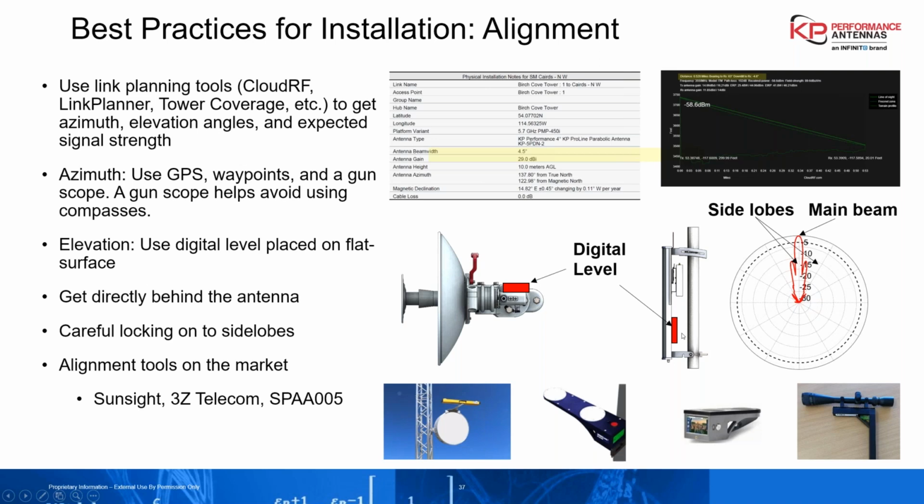On the sector antennas, we recommend the back of the sector, not the top. The reason is these top caps are silicone sealed in place and then riveted, and sometimes this process can cause it to be slightly uneven, and it might be just a 0.2 degree, 0.3 degree, but we know that once you get at a certain angle, you can get very large differences in signal strength on the ground by having a small, half a degree misalignment in the elevation down tilt. So we strongly recommend you use a digital level against the back of the sector antenna.